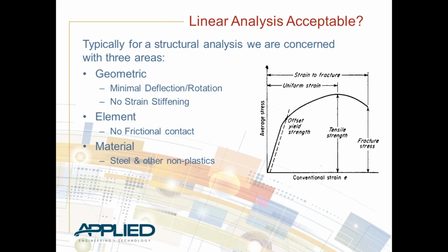All right, so one of the first things we have to determine before we start jumping into an analysis is, what type of analysis are we looking at here? For Inventor Professional, for Inventor Simulation, it has to be a linear analysis. So how do we determine what's linear and what's not? Well, there are a couple things to look at.